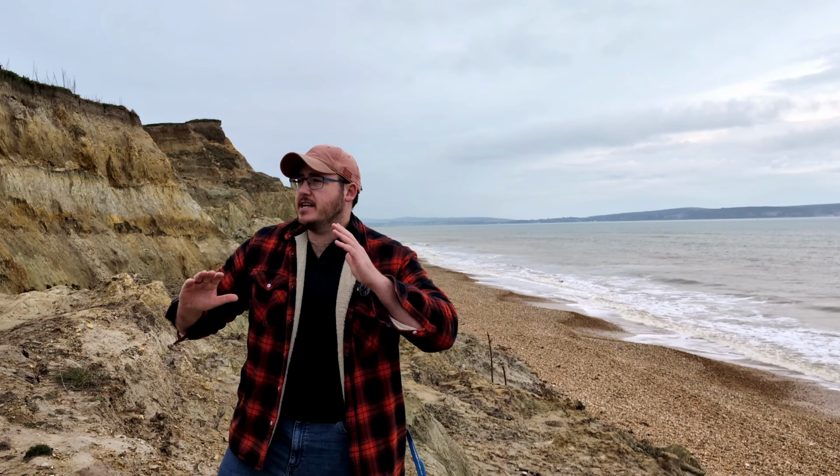important thing. So the goal is to effectively do a linear flight path as we would with an ortho mission. We're going to do a crosshatch mission, and then we're going to be doing an orbital mission capturing 75-degree angle. And then, more importantly, we're going to fly down the coast here, looking back at the cliff face, capturing 45, 55, and 65-degree angles. That should give us enough angles for Agisoft to be able to stitch together a really comprehensive little model that covers pretty much all our bases. We should have really nice terrain profiles, and the same goes for a digital elevation model that we're going to come out with.